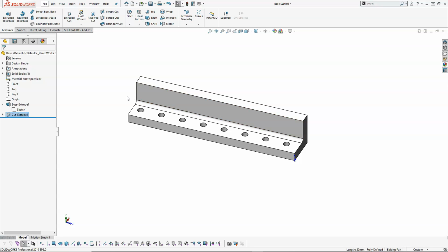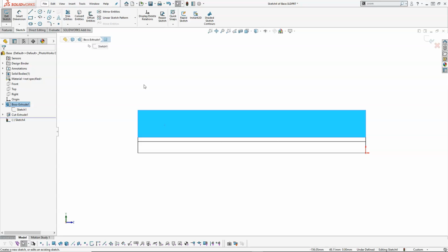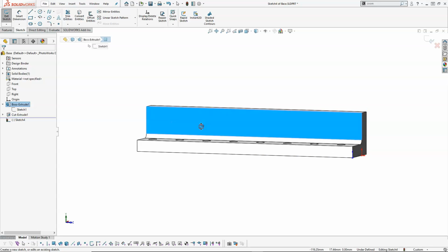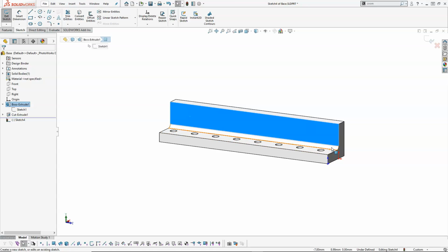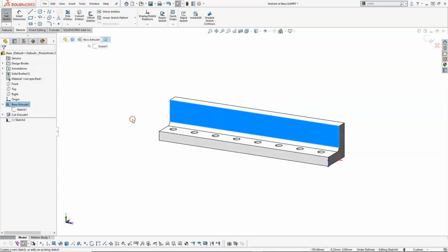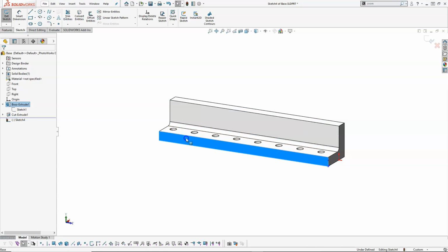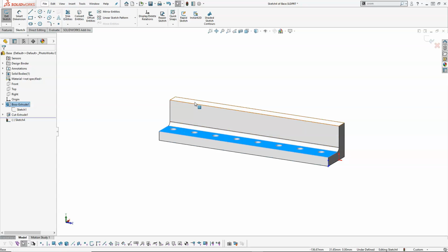The two holes then, we had the radius of 12, so again I can pick on the face and open up a sketch. Once we get past the initial planes, then I can pick on any planar face. If it's flat, I couldn't pick on this arc because of the radius. It would lose its mind. It would tell me I can't. I would have to create an auxiliary plane to pick from. But any of these faces that I can select and right-click and open up a new sketch on are going to put me in that position.